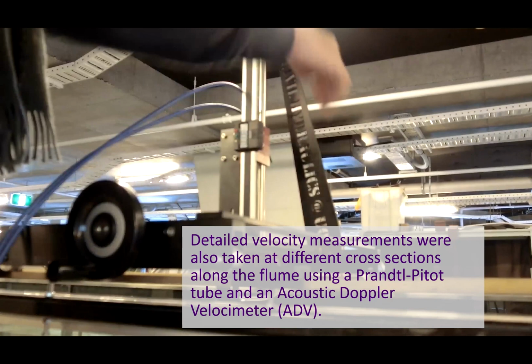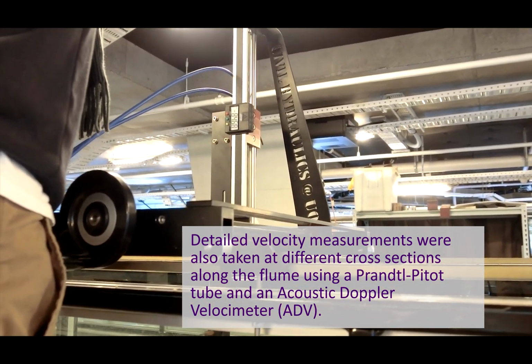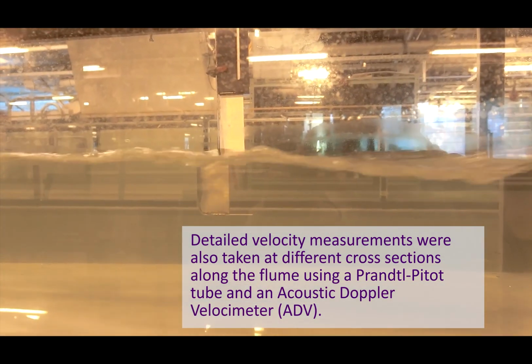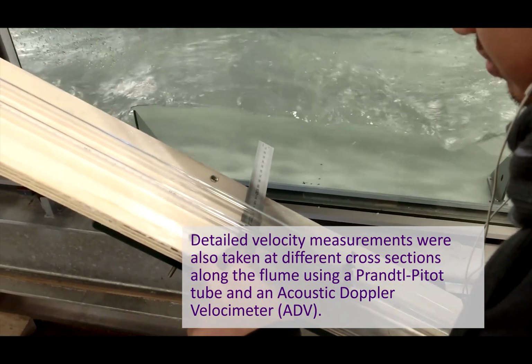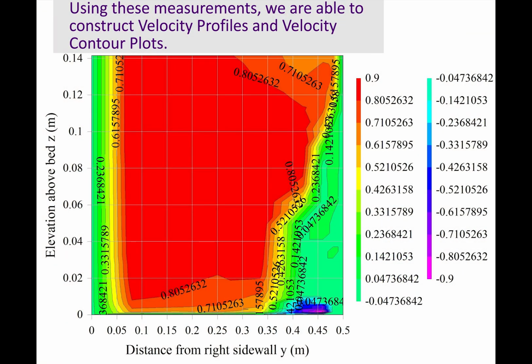Next, detailed velocity measurements were needed. The first instrument used was a Prandtl-Pitot tube, which gives two readings, total head and pressure head. The next instrument used was an acoustic Doppler velocimeter, or an ADV, which provided the flow velocity in 3 dimensions. Using the data collected from both the detailed velocity measurements and the free surface measurements, we were able to construct velocity profiles and velocity contour plots. These results are then compared to previous results to find similarities in the conditions which fish preferred to swim.